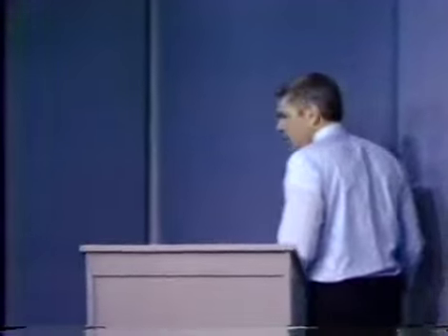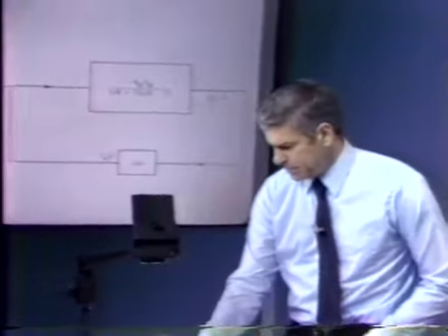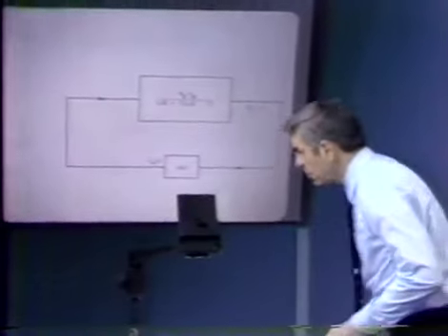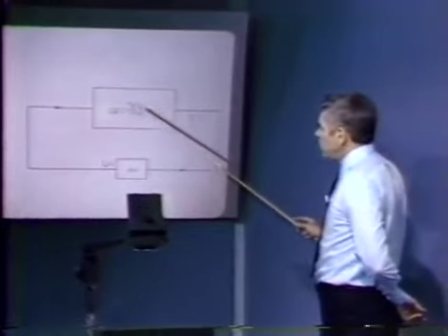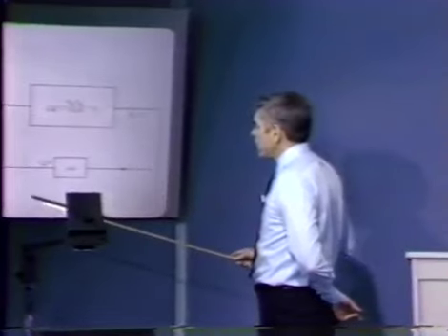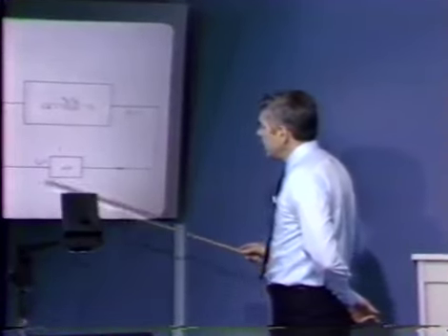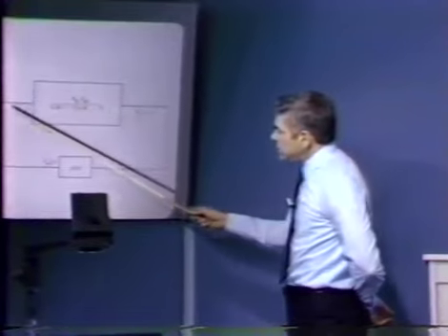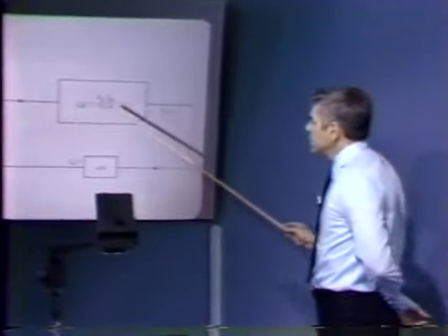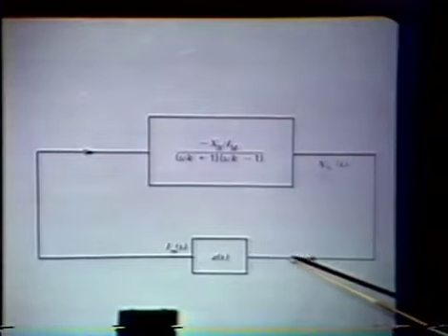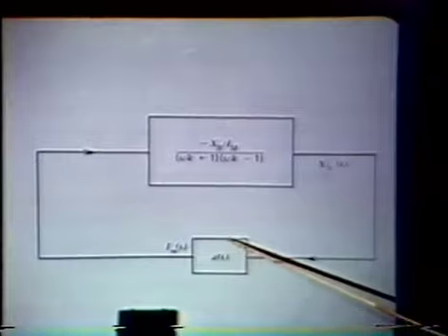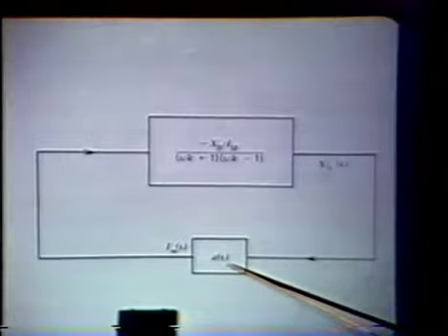Well, we can use that description of ball and magnet dynamics to generate a block diagram for our overall system. So here we have the block that describes the ball and magnet dynamics, the expression we had on the board earlier. We can consider the input to that block to be magnet current. The output is ball position. And then we complete our overall loop by taking an amplifier, an amplifier with dynamics, presumably.